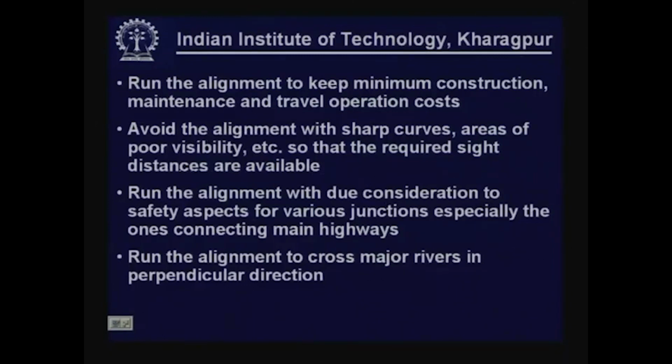Avoid the alignment with sharp curves, because it will be difficult for you to satisfy the design control and criteria. Avoid areas of poor visibility, because that may invite sight distance problems. You are already aware of this requirement of sight distance.